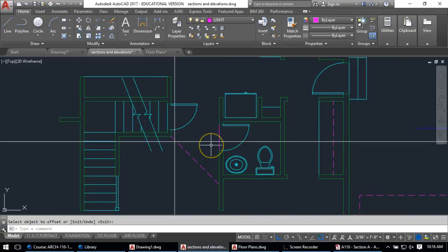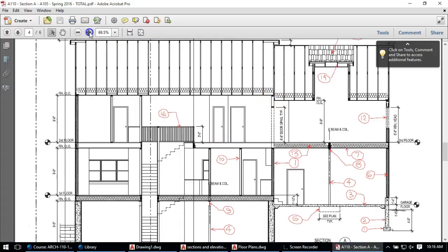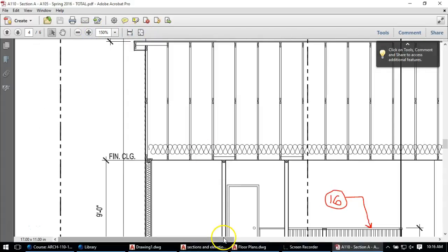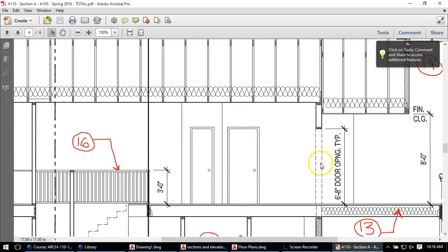But when you cut through a door, you can sort of see it up. Just be careful. Like you can see when you're cutting through a door. I'm going to show you the directions because they do cut through a door in one location, which is up in here. You have to draw the line. You don't cut through this part. It's opening. It's a door. You don't draw the door either. You just draw sort of the opening, right? So that's whenever you cut through a door, make sure you do that.